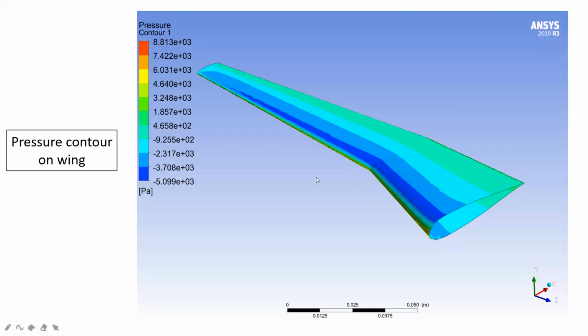And this is the pressure plot on our wing. So you can see that this here is 25 degree sweep from airfoil A to airfoil B, and from airfoil B to airfoil D, you might think is a forward swept wing, but we have calculated in the previous slides that forward swept wing was not the optimized angle. This is 10 degree. If we draw a line here and you measure it, it will be 10 degree sweep. So this is the pressure contour on the wing.